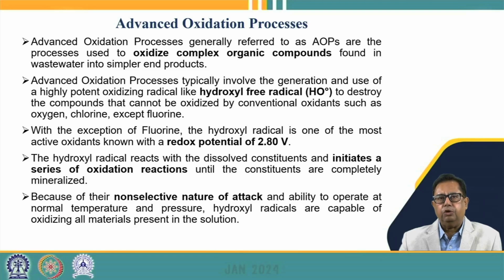So microbes cannot degrade these compounds and in turn they can also die. Okay. So what we can do here is use certain advanced oxidation processes which can degrade these compounds easily, and then the wastewater can become more amenable to the naturally occurring microbes, and they can degrade the wastewater easily. Okay.